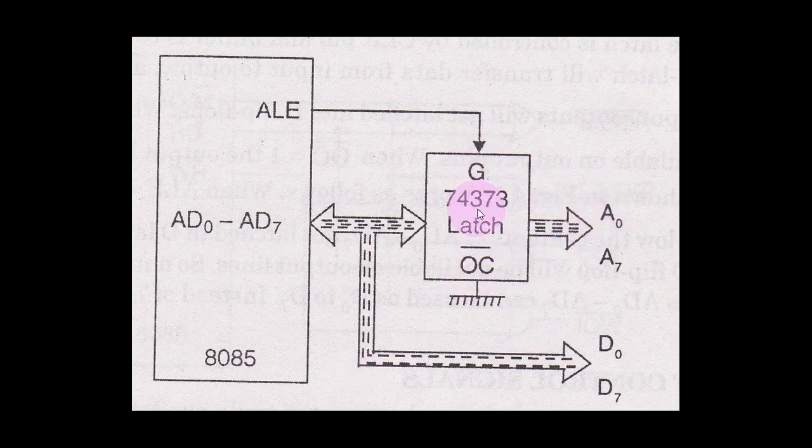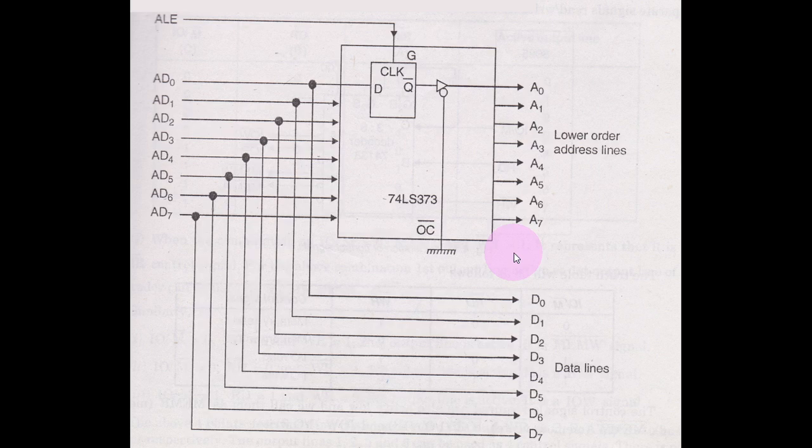Now you will ask a very natural question: what is this IC? How is this address latched? So any guesses? I guess for storing data, you already have D flip-flops. So this is the complete internal structure. You have got a simple D flip-flop for every input to output combination, and this address latch enable is attached to that D flip-flop. So whenever that address is available here, this ALE will activate that particular D flip-flop. So there will be 8 such D flip-flops, and they will all store the same data. And when this ALE becomes 0, that state will be retained as long as you want it to be there, right? And apart from that, there are these 8 lines which can be treated as data lines when this ALE is 0. So this is how the address latching actually happens.